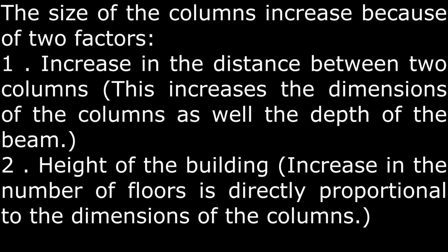The size of the columns increases because of two factors. 1. Increase in the distance between two columns. This increases the dimensions of the columns as well as the depth of the beams. 2. Height of the building. Increase in the number of floors is directly proportional to the dimensions of the columns.